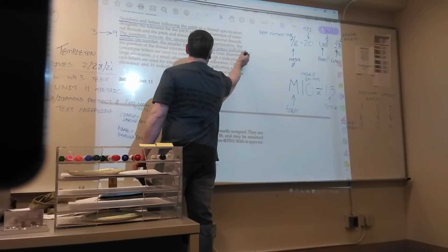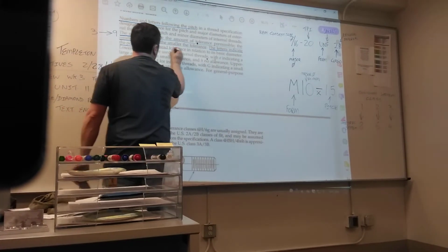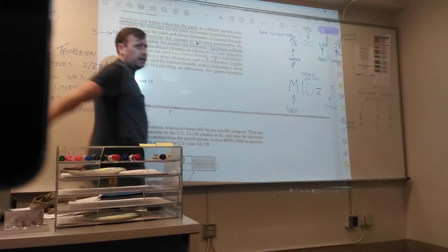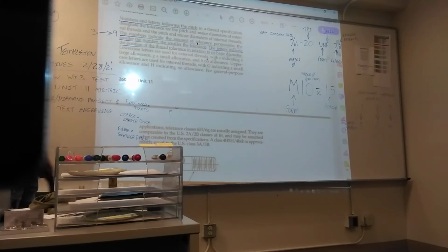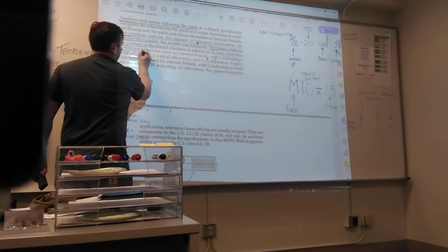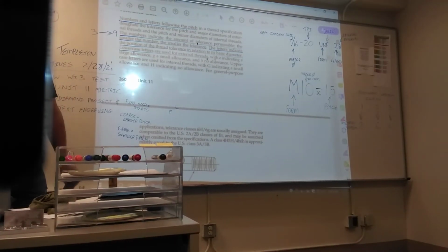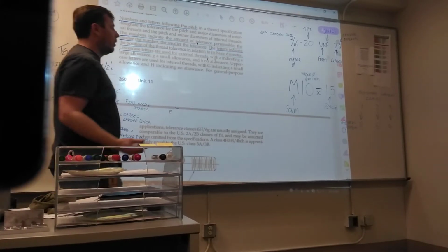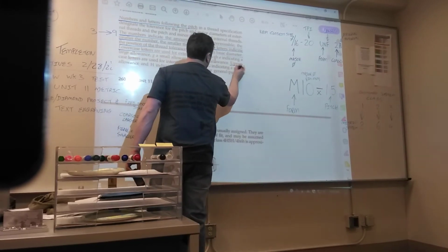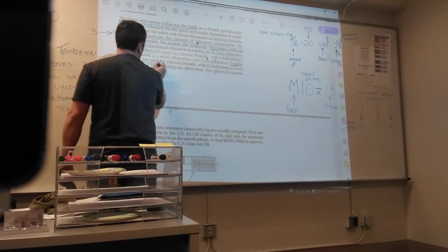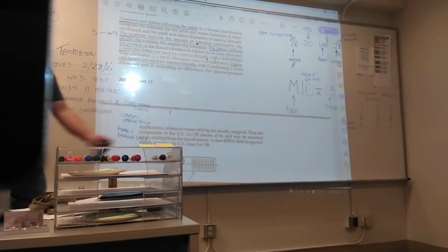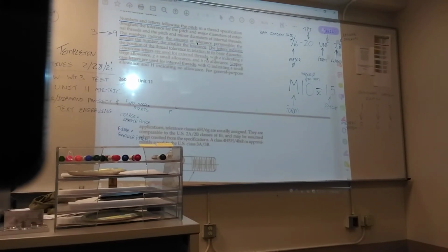After the number, you're going to see some letters. Lowercase letters are used for external threads. So you don't see A or B anymore. You're going to see a capital letter, or uppercase, and a lowercase letter. So lowercase for external, uppercase for internal.